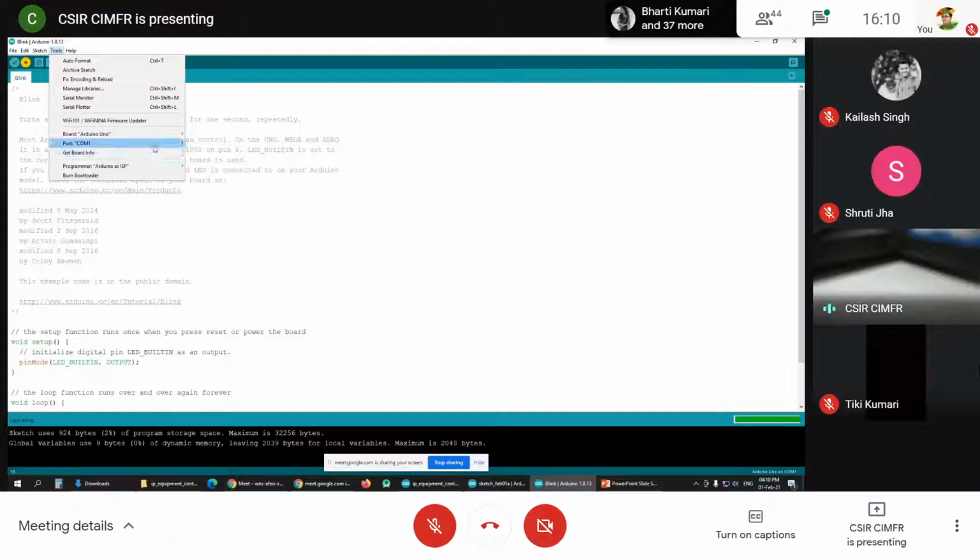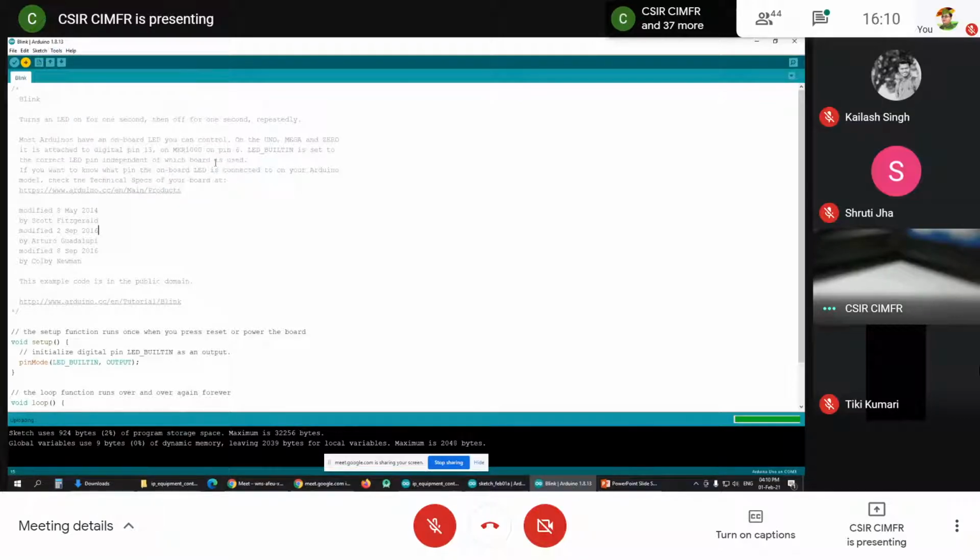Oh, the port we have selected is wrong. COM port 3 is connected to Arduino, so our code is not being uploaded.